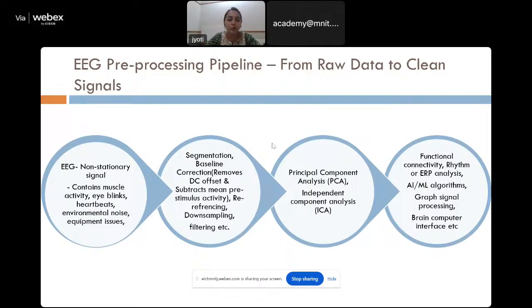So according to the sampling rate, or if we say 10 times the maximum frequency, 1000 samples per second is sufficient. So 5000 is still too much. We can just perform downsampling so that the number of samples per second is reduced, and our analysis will be comparatively faster and computationally efficient. You don't require too many resources when you are doing the calculation. So downsampling can be done. It depends on the situation. All the steps are optional. It is not mandatory that we do all the steps.